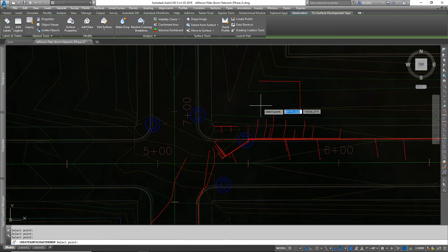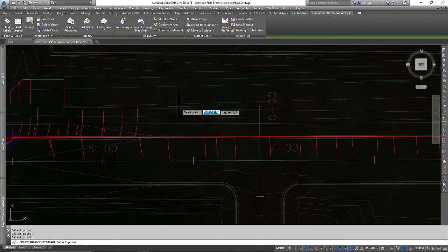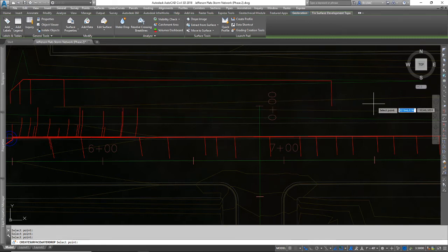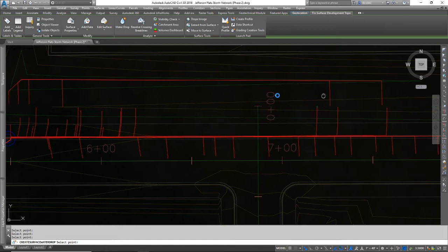But as I go to the north, I've got a different area. This looks like another low spot there. And I can see this pointy contour line here, and water drops are running away from that. So this is a ridge line here. You can see to the north and south of that ridge line, we're going to get flow in opposite directions.